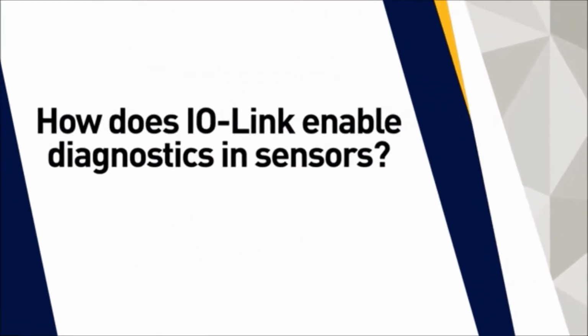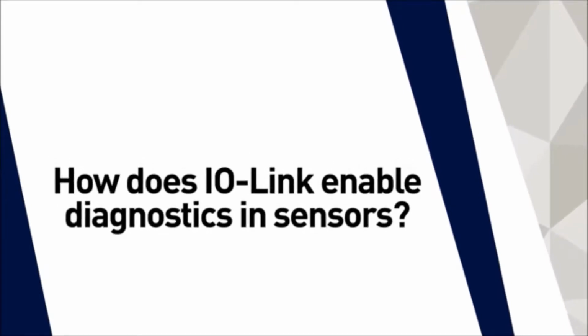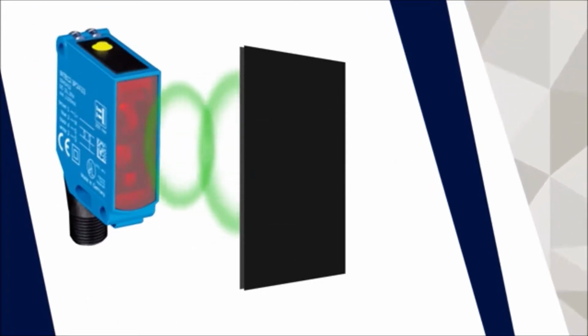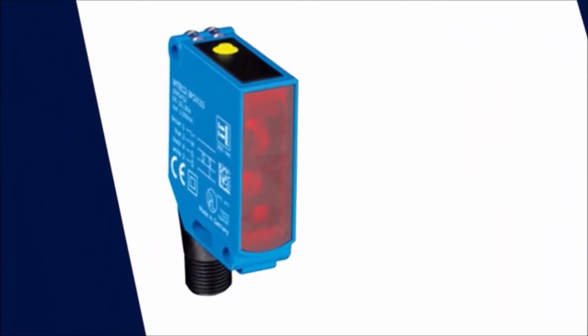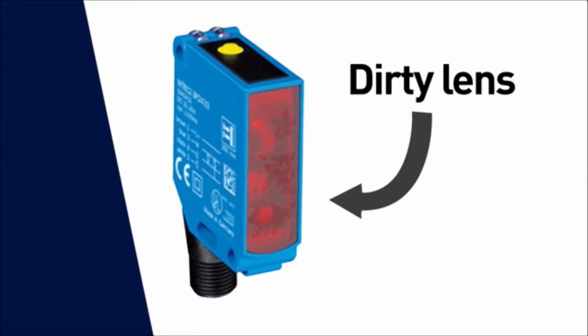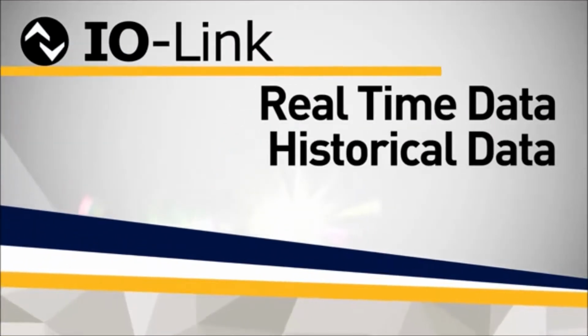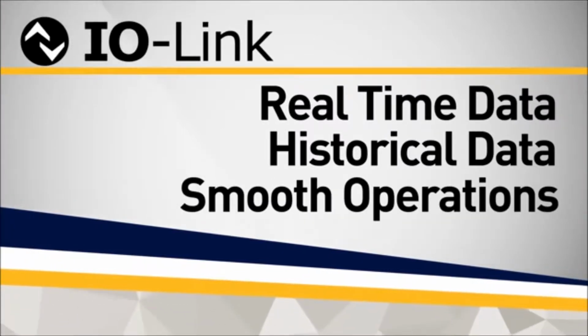An example of how I/O Link enables diagnostics in sensors. Previous situation: it was not possible to tell if a sensor lens is dirty until the sensor fails to sense the target. With I/O Link, excess gain information can be used to check for dirty lenses. Since I/O Link can provide real-time and historical data over the I/O Link network, this ensures smooth operations.